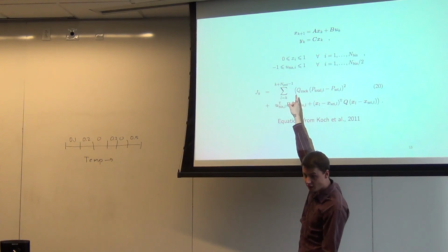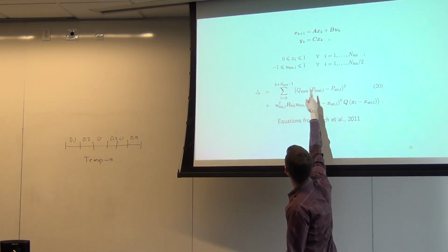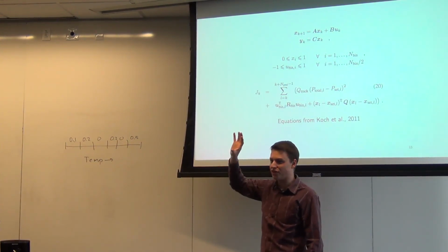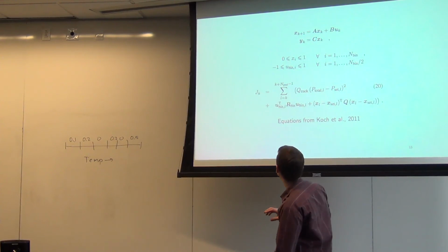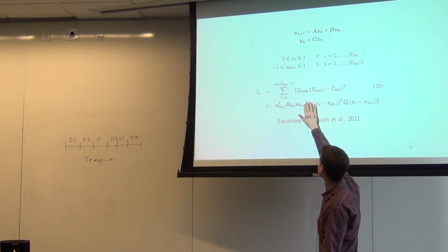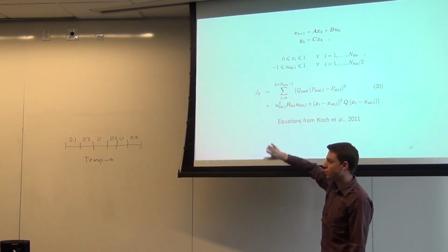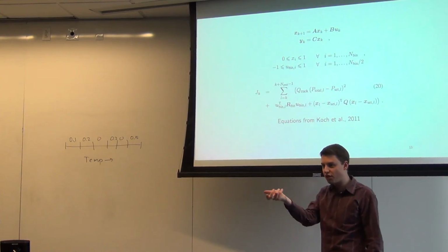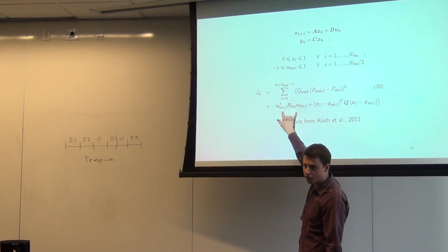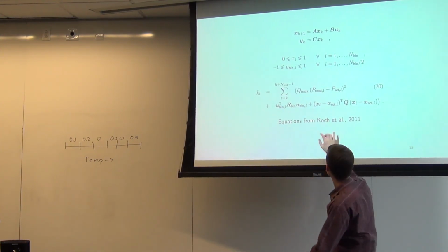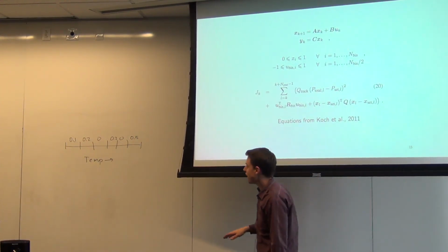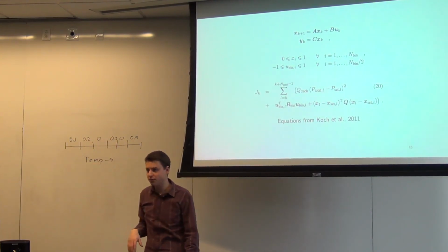They have some constraints on the control. These constrain things, for example, to be a probability vector, and you can never tell people to turn on more than 100% or off more than 100%. And then, given that, you minimize some quadratic costs. This is exactly the form that we see. You basically have some penalty on how much you want your total power to deviate from some set point you specify, plus some cost on the control, on telling people to switch. You don't want them to switch too much, so you penalize that. Plus some deviation from the actual set points themselves. You want them to stay as close to the middle of the range, for example, as possible.